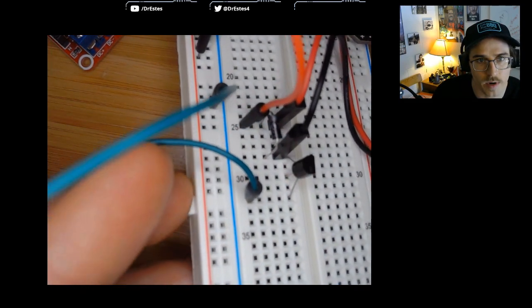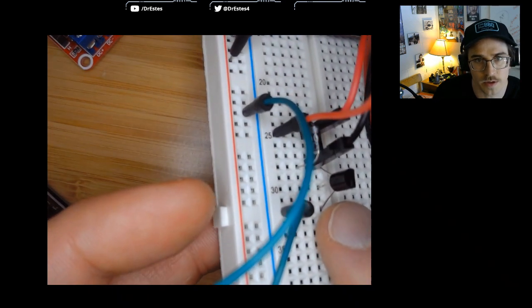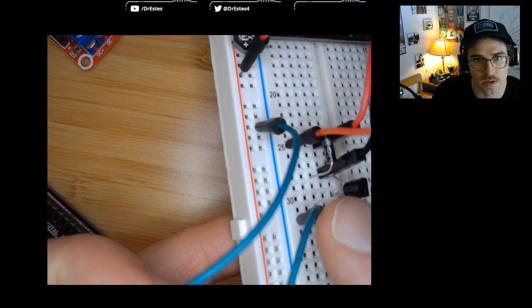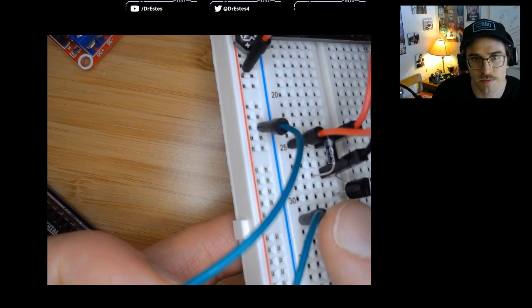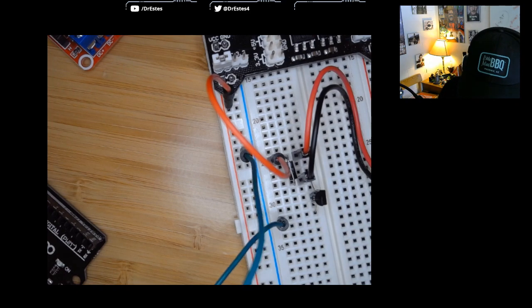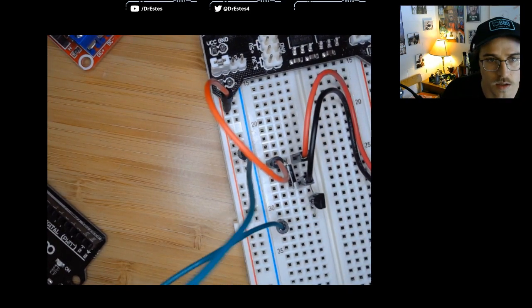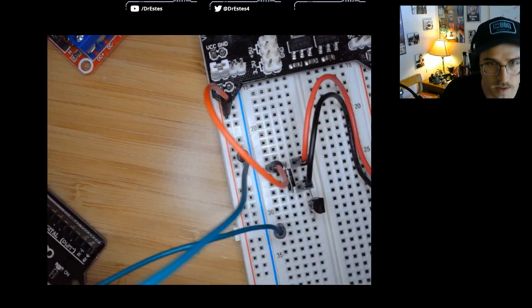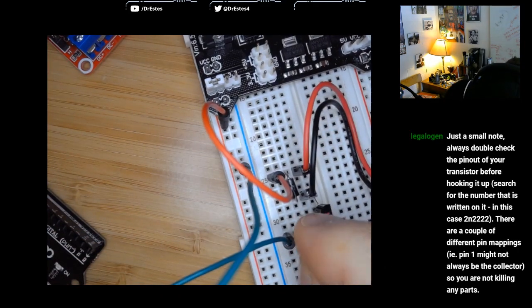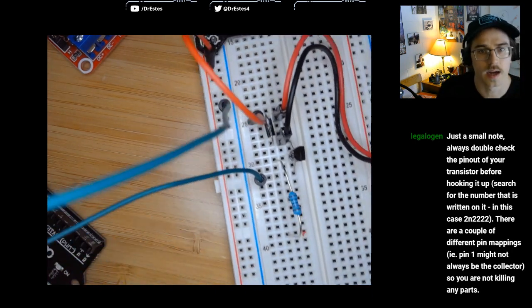Yeah, we got this green wire that's connected to the ground of the power supply, and it's also connected to the emitter. Now, for the base, the middle, we want to connect our 5 kilo ohm resistor, which I already grabbed from the kit. Here it is. Connected to the base, and then I'll have the other leg just somewhere out here.